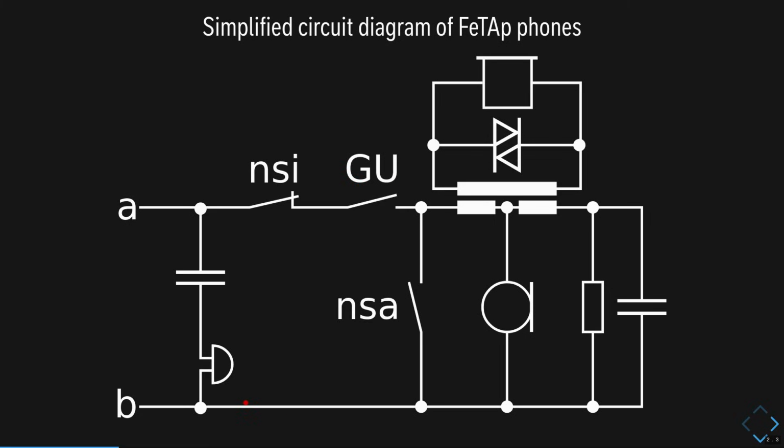And then NSI and NSA are two contacts of the so-called Nummernschalter or Wählscheibe. In English it's called a rotary dial. NSA is called Nummernschalter Arbeitskontakt in German, or off-normal contact in English, and it's closed when you operate the rotary dial. NSI is the impulse contact, or dial pulse contact, that generates the impulses. I'll show that later on.